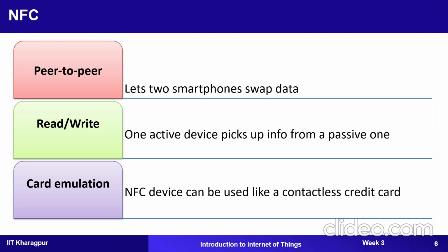The second layer is your L2CAP, that is the logical link control and adaptation protocol. It is layered over your baseband protocol. So basically the first layer is baseband and over that is L2CAP. It is used to multiplex multiple logical connections between two devices and provide connection-oriented as well as connectionless services to the upper layer protocols. It also provides protocol multiplexing capability, segmentation and assembly operation, and group abstraction.